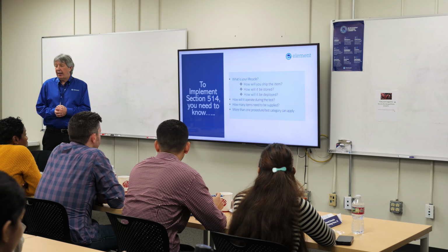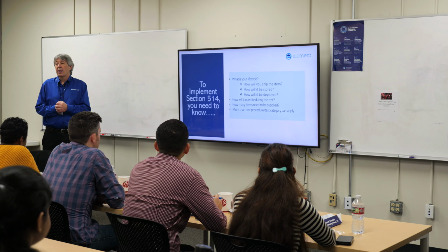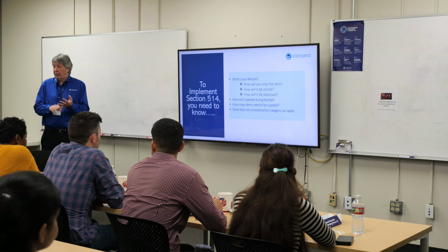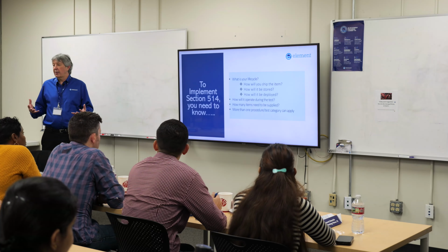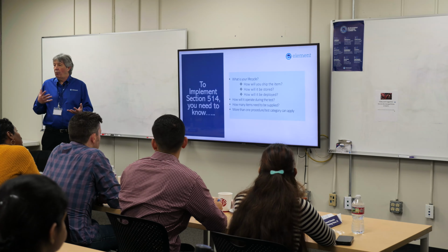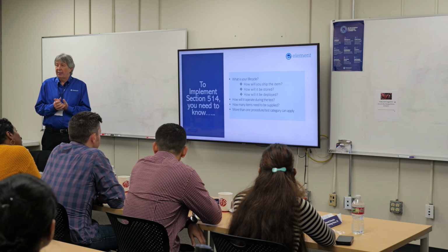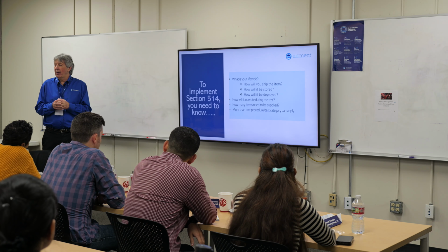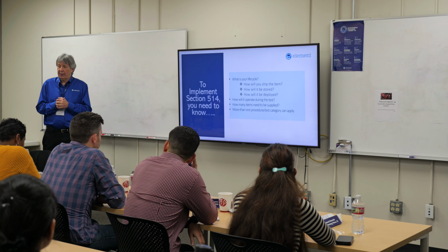There are 4 test categories, 25 categories, 4 test methods. More than likely, you're going to be running 1, 2, or 3 of the different methods. You've got transportation vibration, what vehicle you're on, and all this. So you have to do a lot of research to figure out what curve and how you're going to run. Now, if the DoD is nice to you, they'll tell you and make it nice and easy in the contract. But if you're going after a contract and you're not sure, then you have to work yourself through some checklists, and we're actually going to do that today.